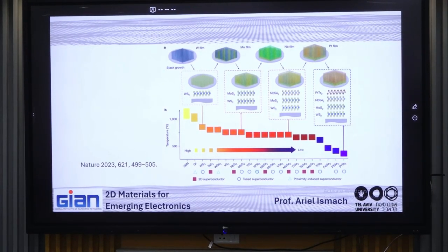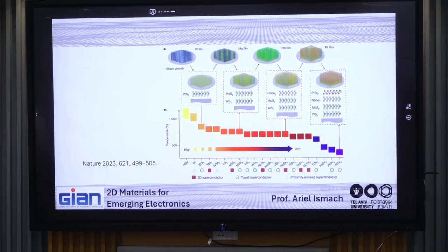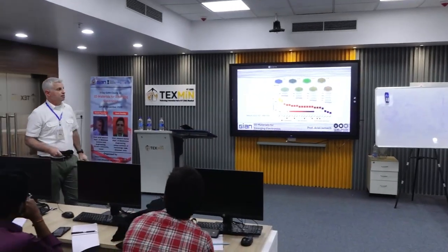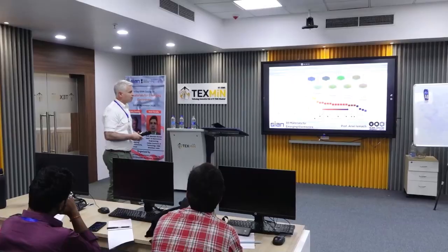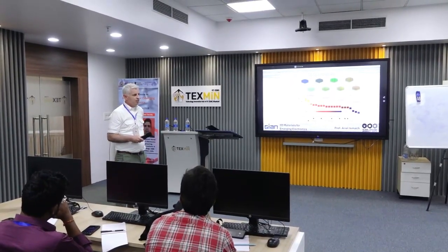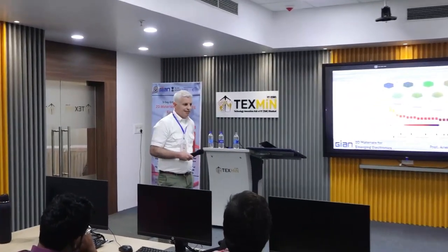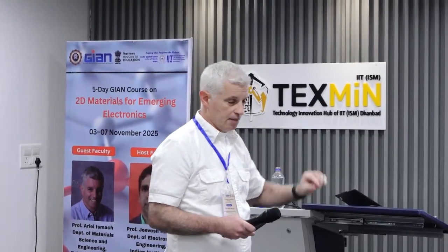Also, for metallization, for every metallization stage, you are using sputtering. Sputtering is one of the only PVD methods. Maybe there are others, but it is the most available method that can lead to very thin layers on specific material systems. When you deposit metal on metal, they have a high adhesion, so high wetting. Therefore, it is possible to deposit very thin films.